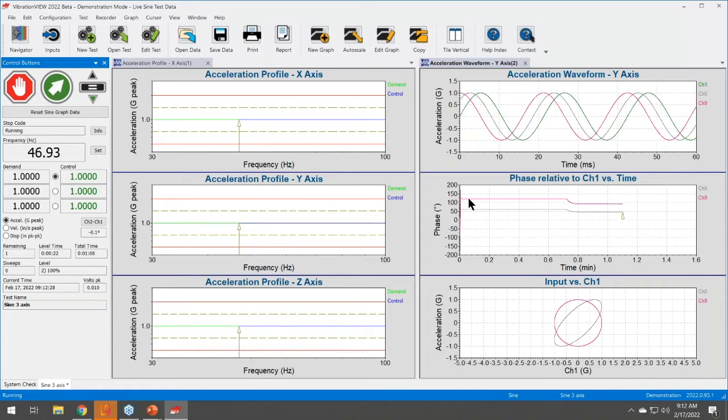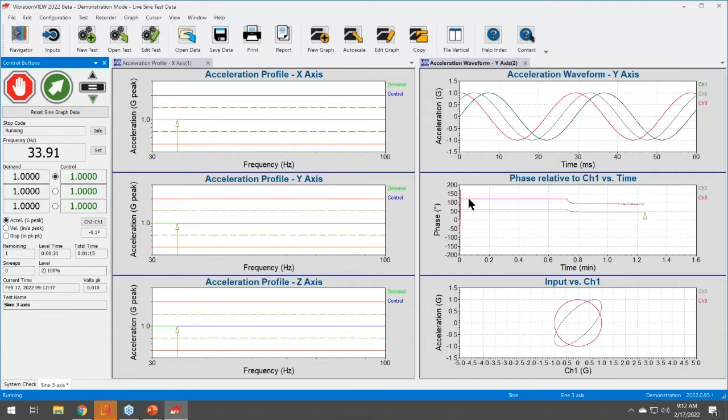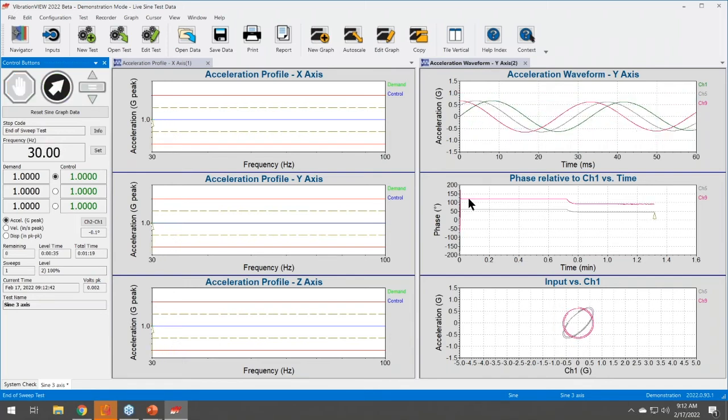they have multiple shakers in parallel, for example, and they're testing a product that doesn't fit on one shaker. So they're using 2 side by side to support the product. For example, maybe a long cylindrical tube or something underneath 2 shakers, or just a large product. Those are some typical uses that we have seen for the dueling shaker, where you're required to have the magnitude in phase to be synchronized.